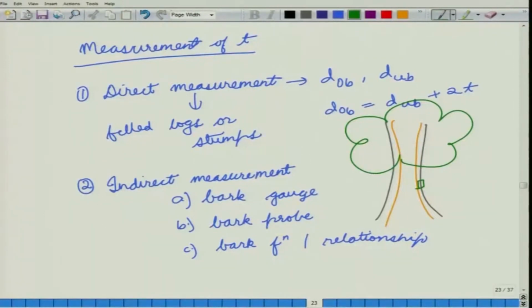Well, that is possible, but the problem with that approach is that bark happens to be an extremely fragile material. So, if this is your bark and suppose while measuring its thickness you put one end of your vernier calipers here, you put the other end here and you try to tighten it, this portion would very easily become compressed to a smaller volume.